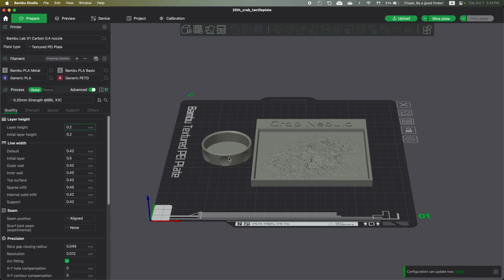So you notice these little divots here for your fingers. This is like a cap that needs to come on and off, but it's going to be a tight fit. So we put these little finger hole grip places. These features are going to be built in the Z direction. The printer has very good resolution in XY. It's got those stepper motors, and it's running very precisely, but it's got a 0.2 millimeter precision going up and down. So it's going to have a bit of a stair-step resolution.